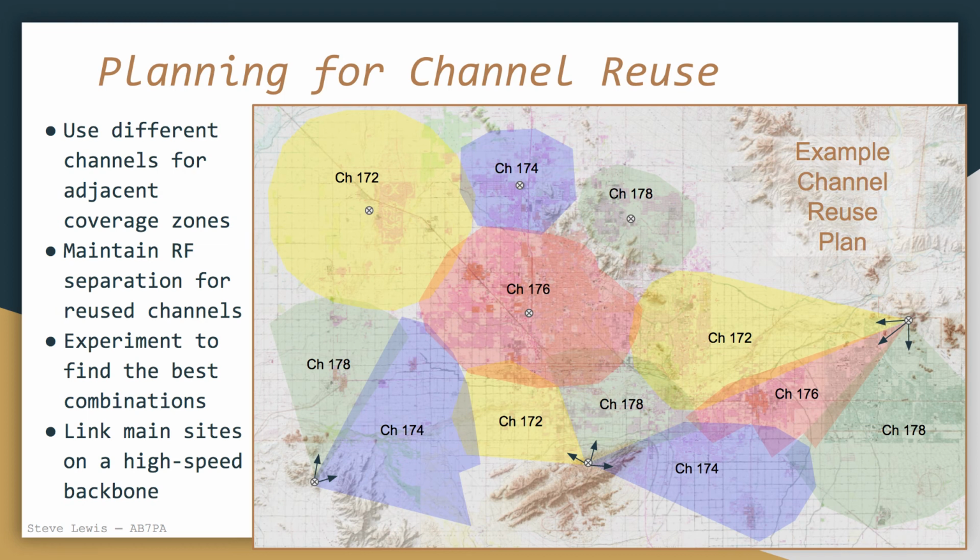Depending on the frequency band you're using, there are various options for assigning non-overlapping channels to your mesh devices. As we saw before, in the 5.8 GHz band, using even-numbered 10 MHz channels, there are 27 non-overlapping channels for use. Each adjacent RF coverage zone should use a different channel, and they can be overlapped slightly to provide broader connectivity, but adjacent coverage zones should not use the same RF channel.